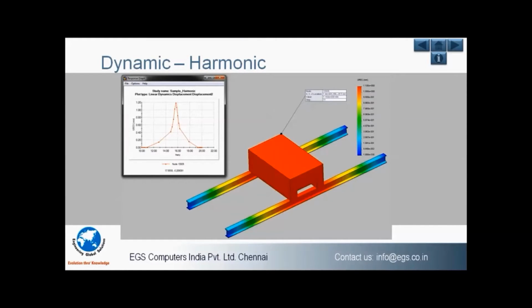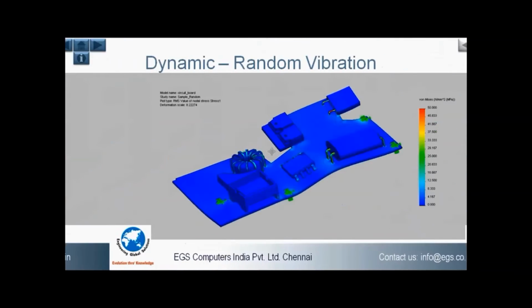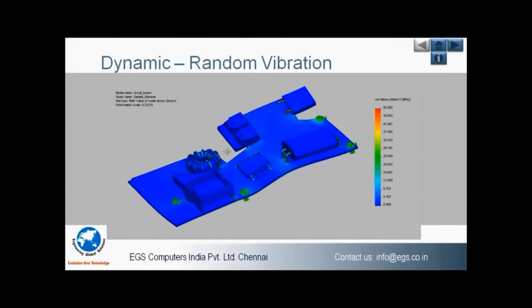SolidWorks simulation can also perform complex analysis for different applications. When you are dealing with the mass, velocity and acceleration for the product designs, obviously we must directly study the physics of the problem or the dynamics of the problem. We can study the harmonics and the modal analysis using the dynamic simulation, or we can even perform a seismic analysis using the response spectrum.